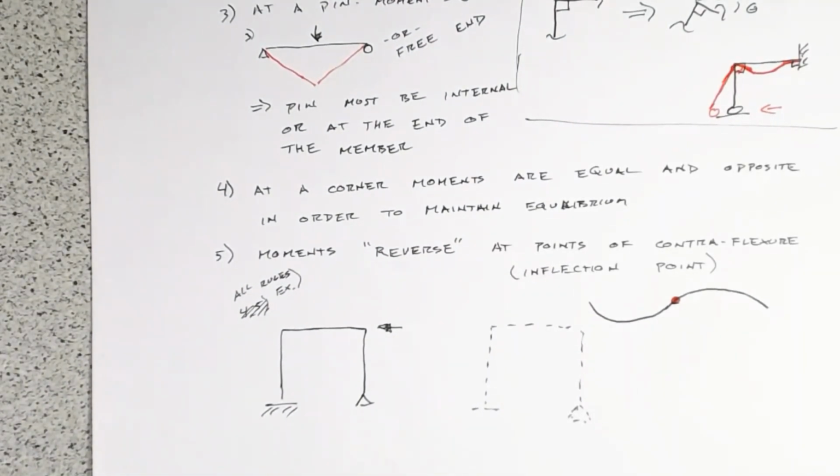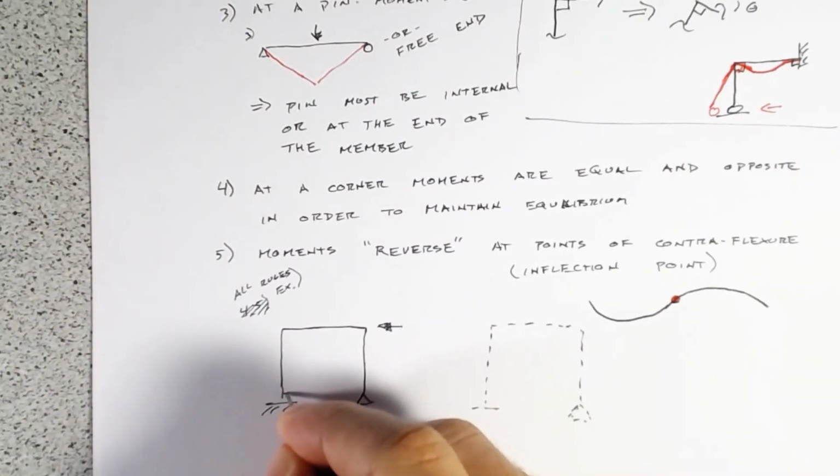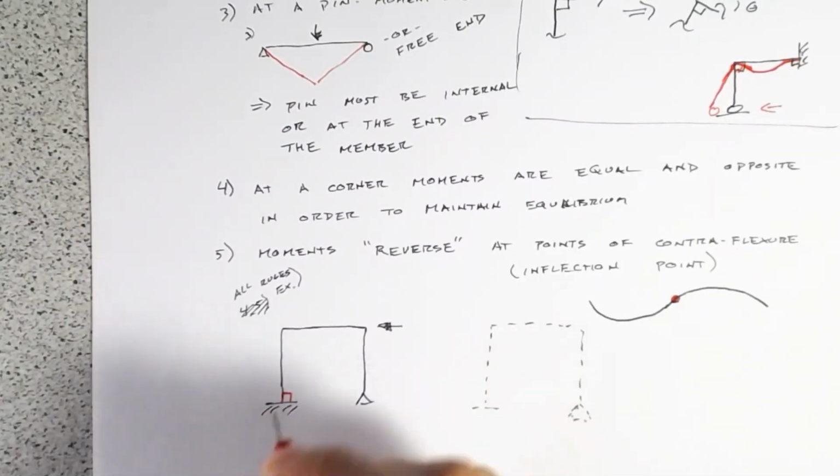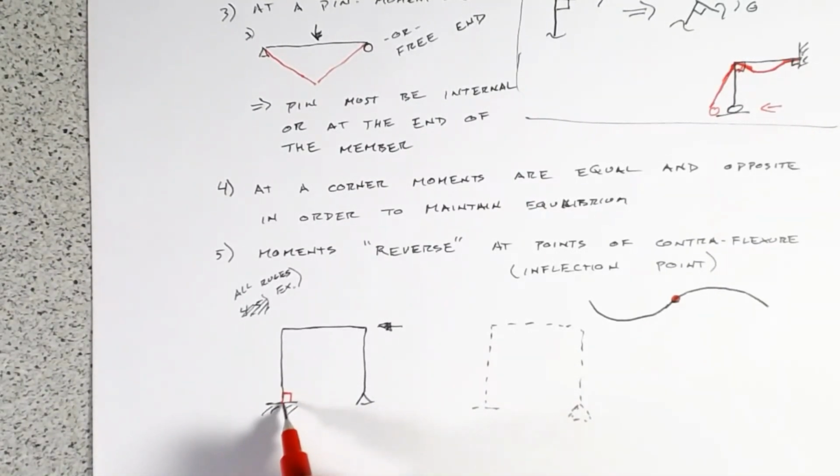So how would we tackle this problem? Well, what's the relative bending moment demand? The easiest thing to do is just start with the deflected shape. When doing the deflected shape, you can break it down into pieces, and you can think about, well, what do you know? Well, we know that down here at the bottom, we have no rotation, no movement.